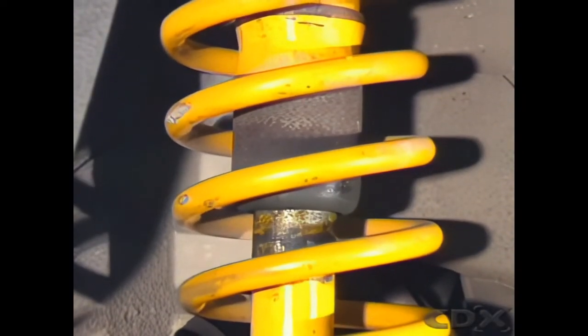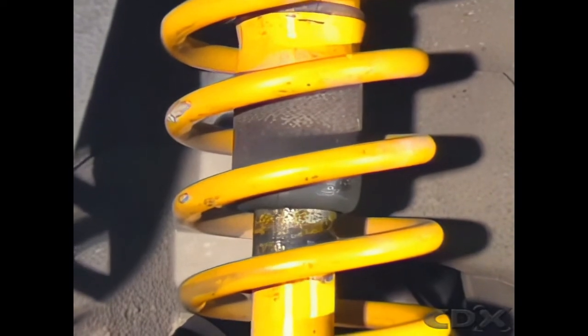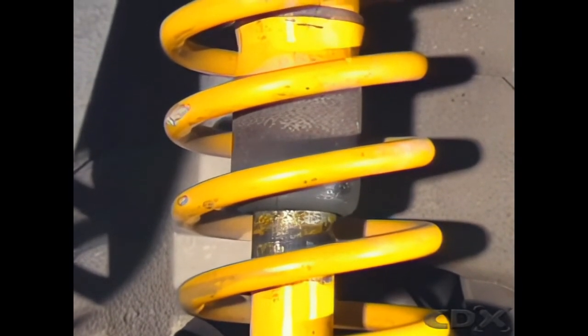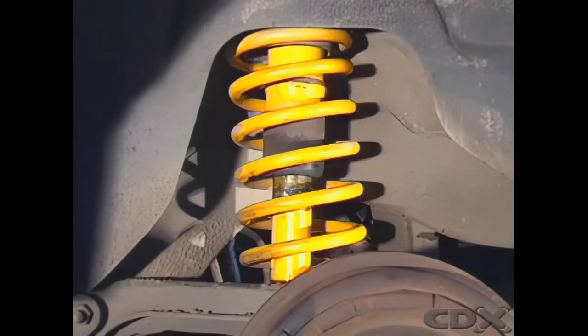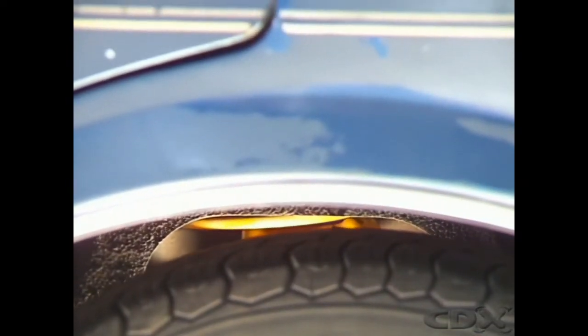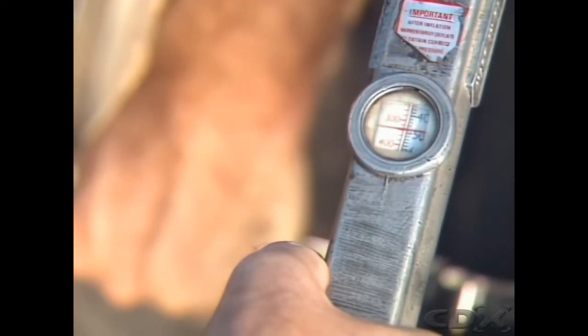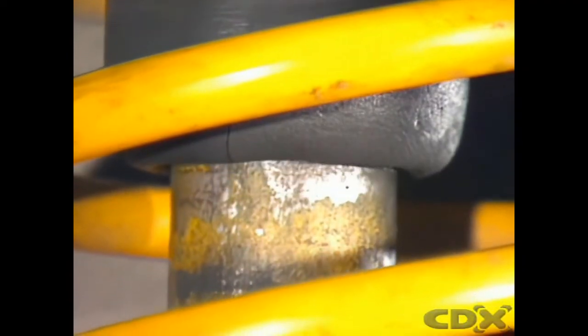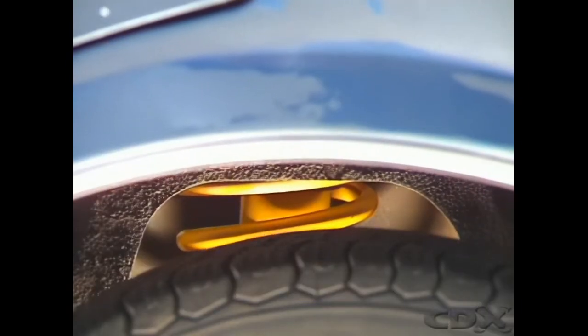The air spring consists of a flexible rubber cylinder which seals the outside of the upper and lower halves of the shock absorber. The shock absorber is a standard hydraulic type, providing normal dampening action. But when a heavy load is placed on the rear of the vehicle, the rubber air cylinder can be pressurized to assist the suspension springs. By changing the air pressure in the cylinder, the ride height can be adjusted, as well as the stiffness of the suspension.